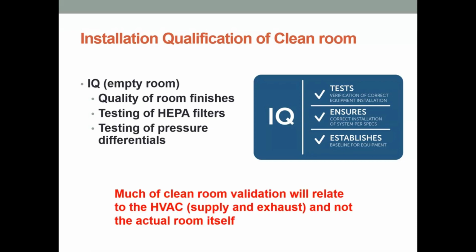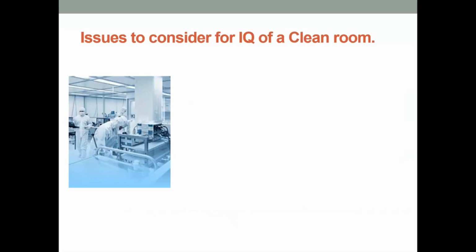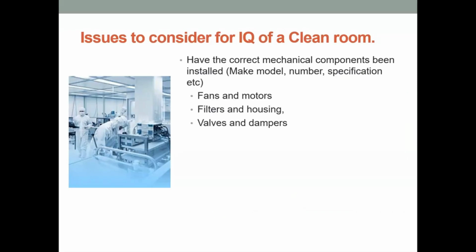Much of a clean room validation will relate to the HVAC, so the supply and the exhaust of the air, and not the actual room itself. Issues to consider for an IQ of a clean room. Well, number one, have the correct mechanical components been installed? So you would be going to verify the make, the number, and the specification of all your mechanical components and checking that they're all tagged correctly. You'll be looking at your fans and your motors, your filters and your housing, and your valves and your dampers.